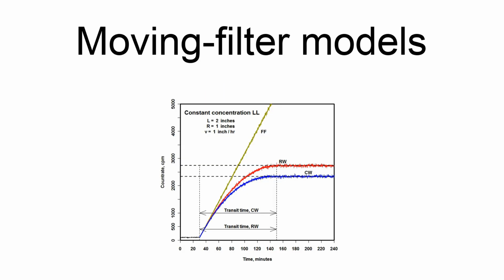For the moving filter CPAMs, the above expression is a starting point, but the models are considerably more complicated, due to 1. The loss of material as the filter medium moves away from the detector's field of view and 2. The differing lengths of time that parts of the filter medium have been exposed to the sampled air. The basic modeling approach is to break down the deposition regions into small differential areas and then consider how long each such area receives radioactive material from the air. The resulting expressions are integrated across the deposition region to find the overall response.